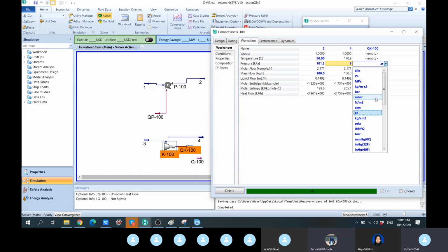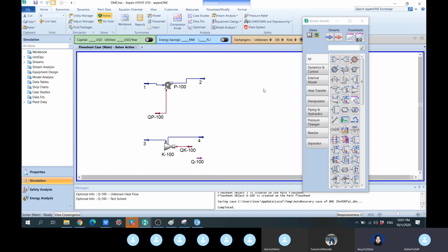It's already at the higher limit as well. So 8 bar, 8 atm, 159, still at the highest limit. What matters is then this temperature limit, and then we need to check with the vendor, or you can just Google this yourself: the temperature allowable limit for a certain compressor, or the compressor that you are using. So is this clear at this point in time? Yes, yes. Very good.